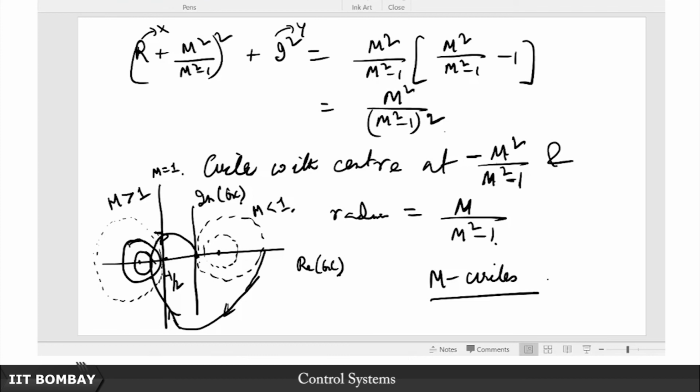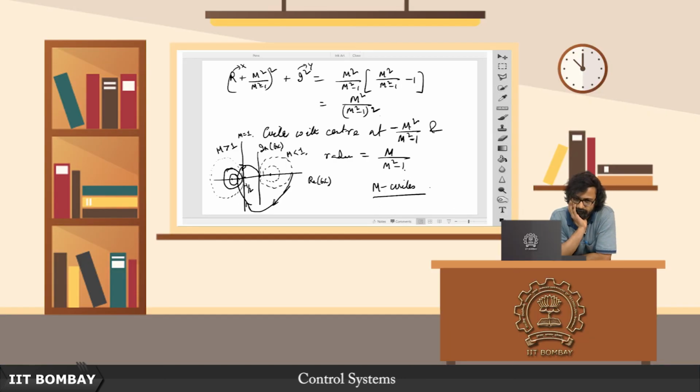So suppose I have a graph paper on which I have already drawn a lot of these circles for different values of m which interest me, and on that graph paper I superpose my Nyquist diagram. Then the intersection of the Nyquist diagram with these circles will exactly tell me at what value of frequency, or omega, I will have exactly that closed loop gain.